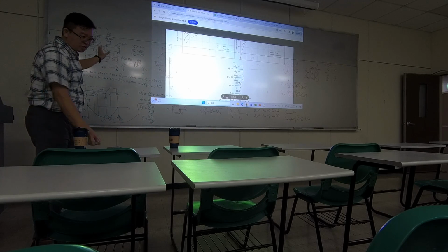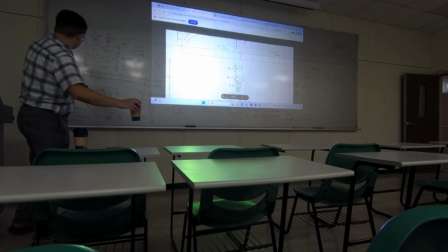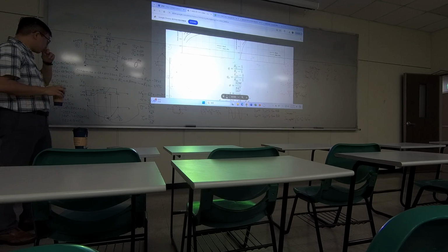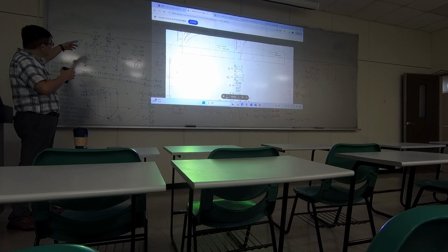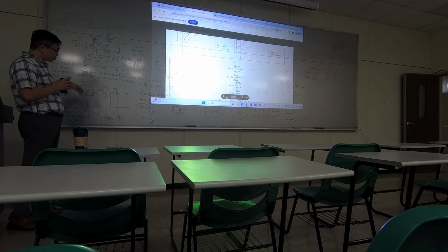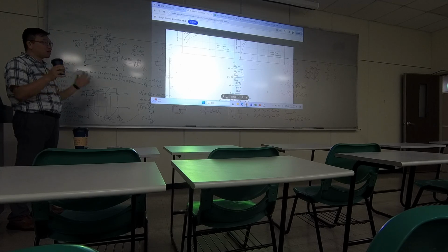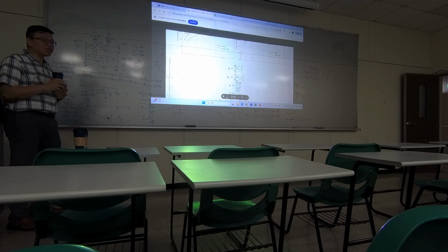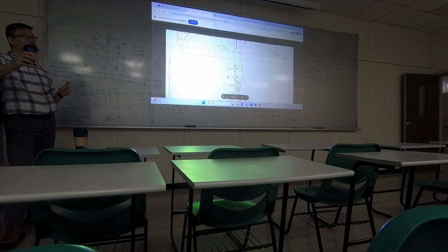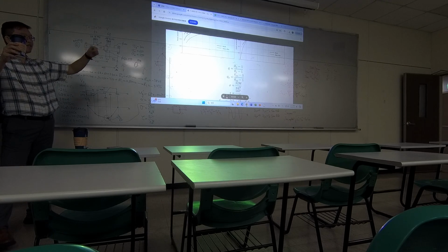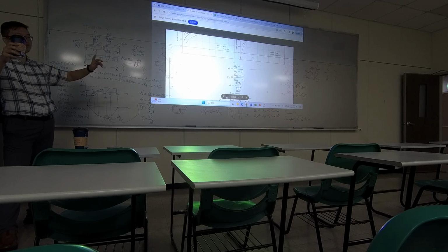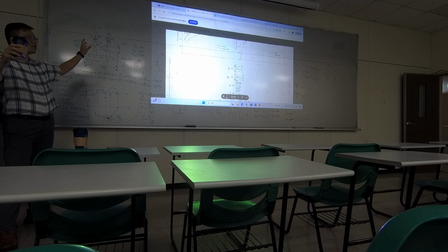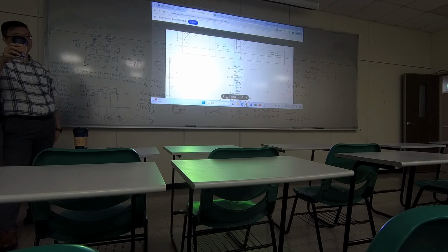Start from the shaft analysis, finding out the worst loading position, and then try to study what's going to happen when the shaft is rotating. And you realize the bending moment and the twisting moment doesn't change with time. The only thing that's changing is the position of the element on the shaft. So bending moment and torque doesn't change with time. The amplitude part of N and T are 0.